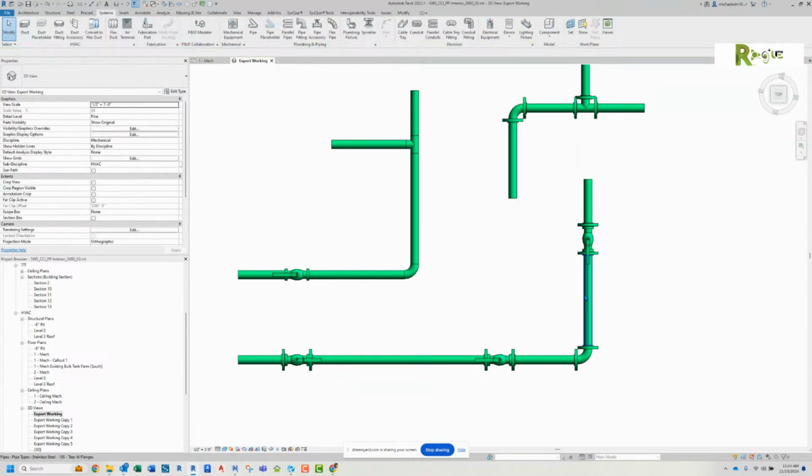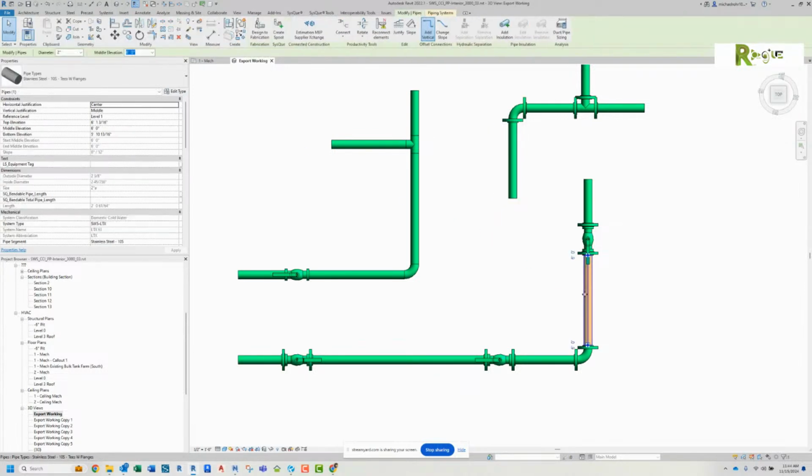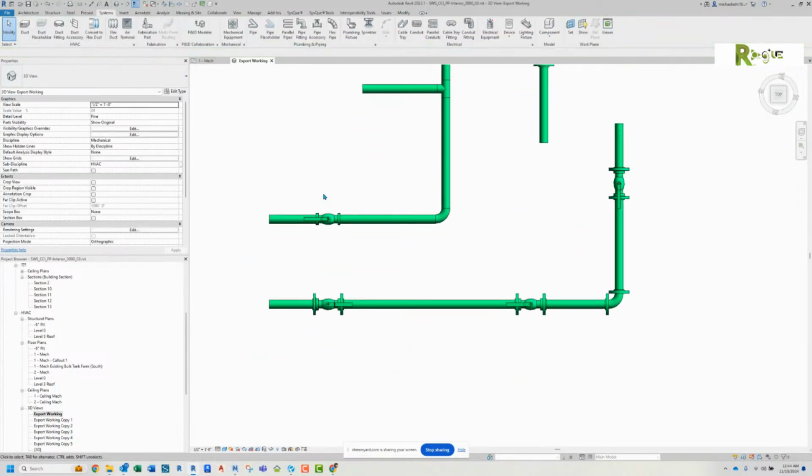So Mike, go to that one pipe that's next to the ball valve and switch it to the flange one. No, not on that one, the other one. The other pipe system to the far left. Isn't that the one you want? Is that not the correct one right there? Right, so this one right here? Yep, then switch it to the flange one. And then now break the pipe right before the valve.